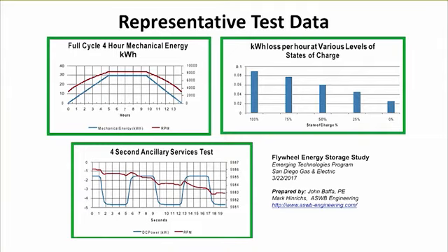Then on the lower part is a transient response, and this is relevant for the frequency regulation function, where high-speed responses are necessary. Things are really limited by communication, and I'll show another overview diagram in a moment, but we see that it's actually a third-party inverter that connects to the utility. And so we can't be any better than a third-party inverter can.